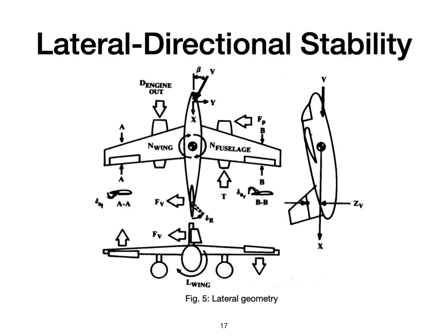Yaw and roll moment equation and its trim. The figure shows the major contributors to yawing moment N and rolling moment L. Yaw and roll are positive to the right.